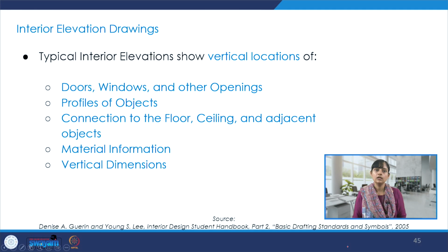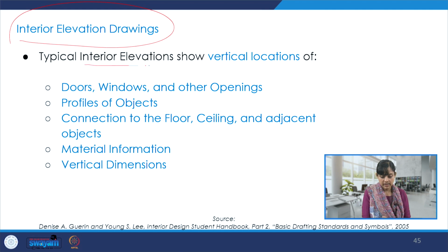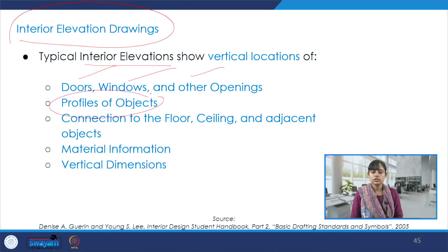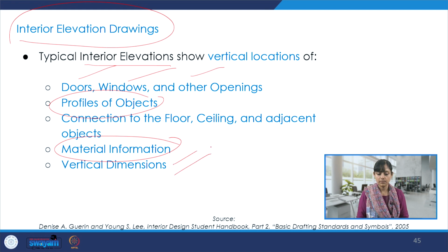Interior elevation drawings, like I said, they are very important, and we could keep adding a lot of details. We could keep adding a lot of numbers and make elevation drawings from different angles, positioning the subject at different points. And the interior elevations could show us doors, windows, other openings, even profiles of objects, connections between the floor and ceiling and so on, the information about the material palette, and of course the dimensioning and notation to highlight the information.